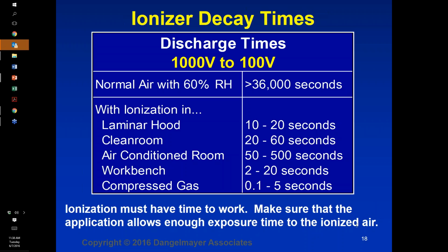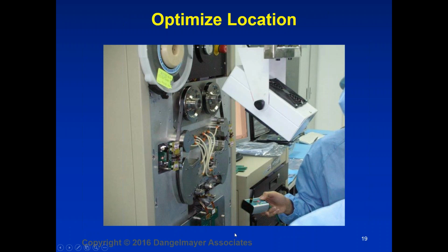Humidity is much more effective at lowering the charge levels that are created triboelectrically. When you have a layer of moisture on two objects, you no longer have quite the dissimilar two objects being in contact and separation. What you have is two layers of identical moisture in contact, and the charge generation levels tend to be much lower. But as far as removing the charge, once it exists, humidity is very ineffective.